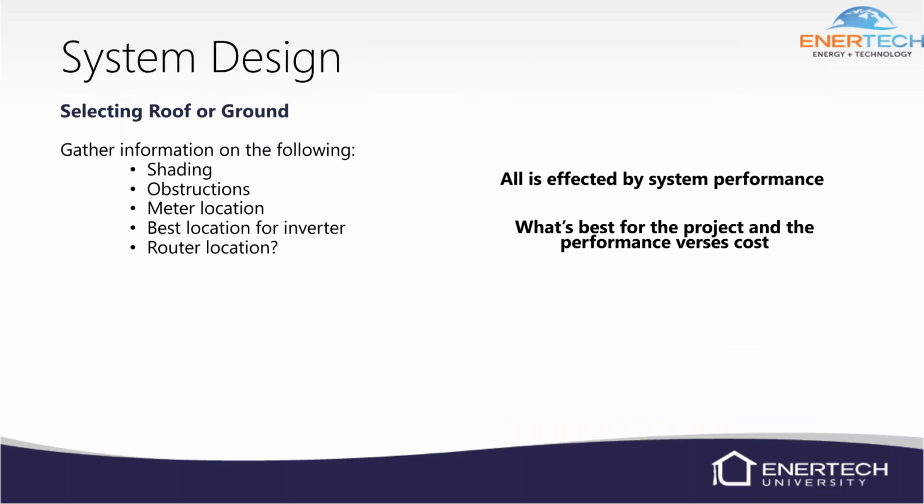System design, selecting roof or ground mount. Gather the information on the following. We're going to have to check shading, any kind of obstructions, the meter location, where you would like to locate it, the best location for the inverter, and the router location. Those are all things you're going to have to take into consideration. Obviously, if they don't have anywhere in their yard to put it, then you're almost going to have to go on the roof.